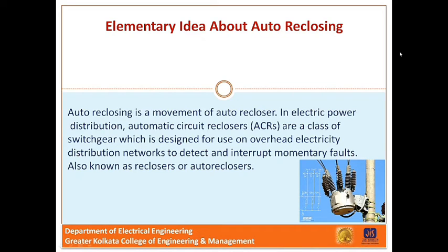However, the fault could quickly clear itself as the limb falls to the ground. If the only protection system is provided by breakers at the distribution substation, large areas of the distribution network could be blacked out while repair crews reset the breakers. So reclosers are programmed to automate the reset process and allow a more granular approach to service restoration. The result is increased availability of the supply.